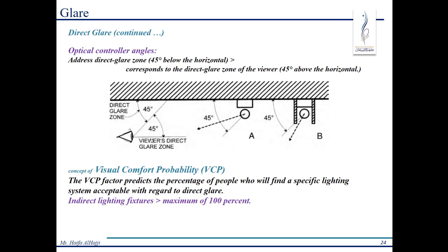So all of these luminaire covers should take into consideration where the viewer is standing and how he's going to look at it or not. Will he be sitting in which area? So you have to take all the geometry into consideration. Sometimes you can't accommodate all the directions for everyone, so sometimes you just want to accommodate at least a percentage of people. Now, in our optimal design, we need to cover the maximum 100% of people not seeing any type of glare. But sometimes we are going to achieve, for example, 90% of people not experiencing glare from this light source.